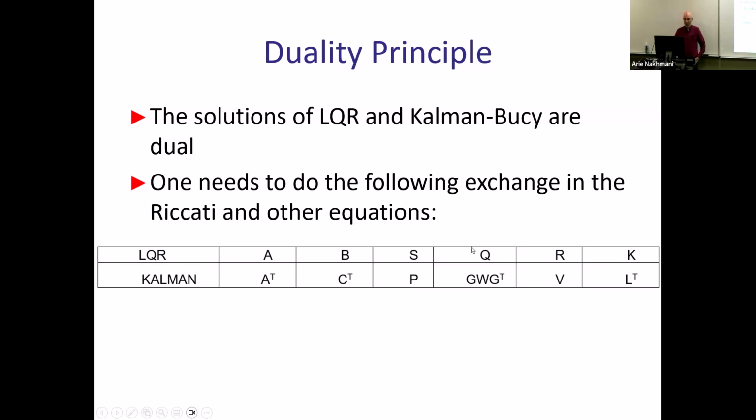These are the variables that we used for LQR. So these are matrices A, B of the system, the original system. This was the S matrix, Gramian, if you remember, which was a Riccati equation variable that we needed to find from the Riccati equation. Remember that matrix, n by n matrix, which needs to be a positive definite solution of the Riccati equation. Okay, and then we wrote K as a function of that S.